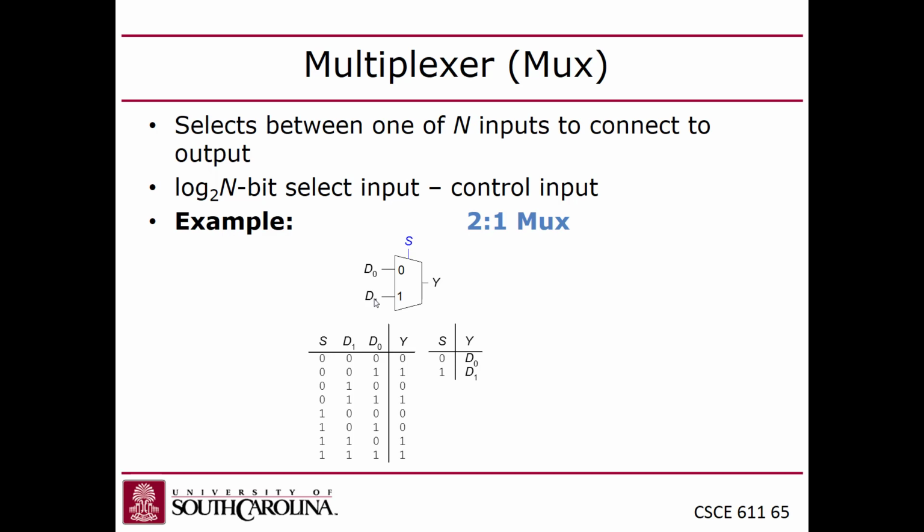It's like a single operation that's done by the CPU. But inside the CPU, once you get under the hood, each instruction is implemented using data paths by establishing pathways through different functional units and register files and registers on the CPU. And the way that all works is with multiplexers.